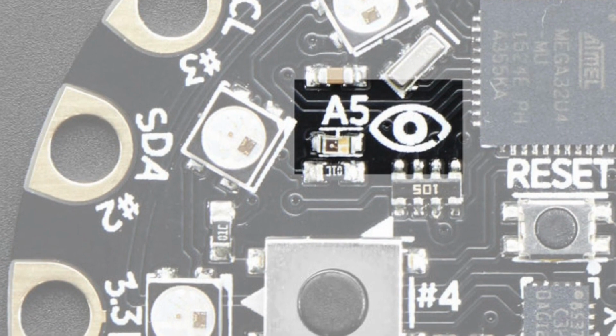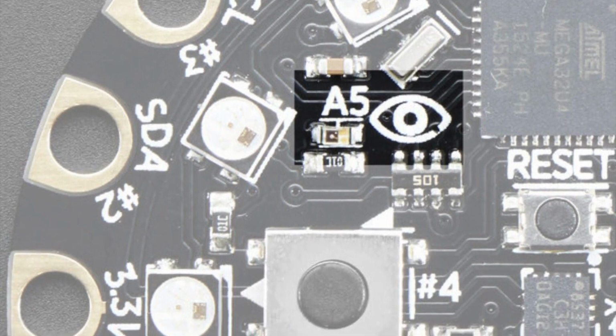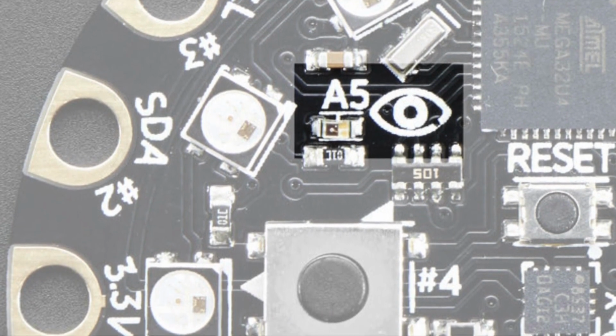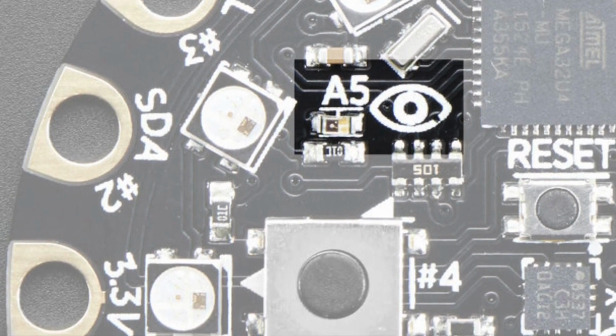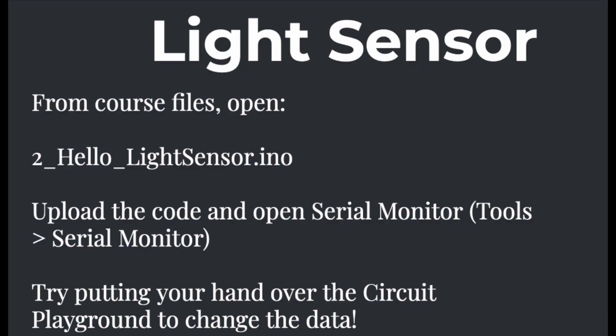We'll use the following sketch in order to tell what the average light level is for your environment, as well as what is dark or bright for your environment. Open the sketch Hello Light Sensor from either your course files or from the Adafruit Circuit Playground library. Upload the sketch and try putting your hand over the Circuit Playground, then taking it away to see changes in the data in Serial Monitor.